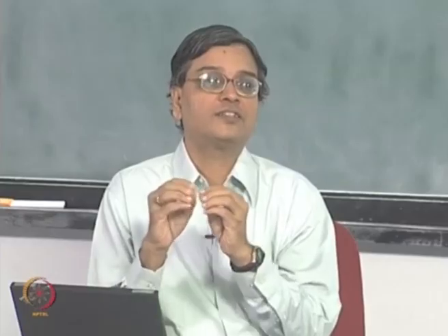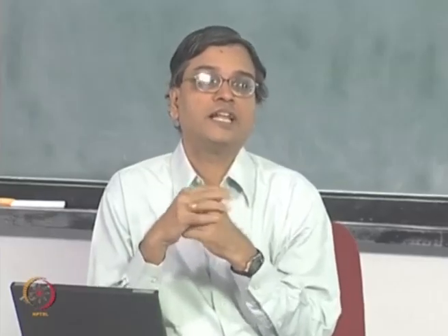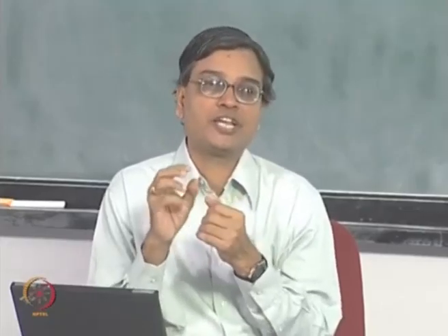But what I will do now is, you take my word for granted at this stage of the course, and in the present example the contours observed are isochromatics, depicting contours of principal stress difference. And for you to understand this, we have to develop crystal optics. Nevertheless, if time permits, towards the end of this lecture itself, you will be able to appreciate from a solid mechanics point of view how one can say that these contours are sigma 1 minus sigma 2 contours.